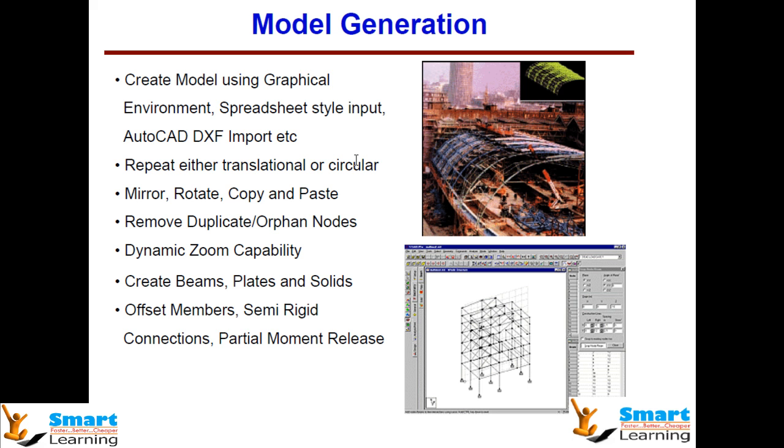If you see the model generation technique, you can use Staad's inbuilt graphical user interface for creating your model. You can import AutoCAD DXF format. You can repeat the operation within Staad by using mirror, copy, rotate and translations, or you can do the paste.